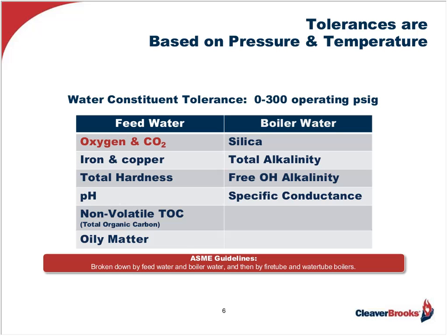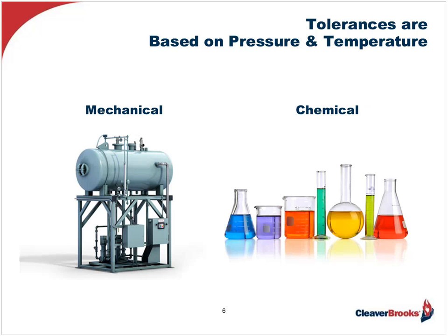Now, the other impurities are controlled through a good water treatment program using water treatment equipment, and then applying various chemicals in conjunction with proper and consistent monitoring, dosing, and a surface blowdown routine in order to eliminate scale formation, corrosion, and carryover of boiler water into the system.